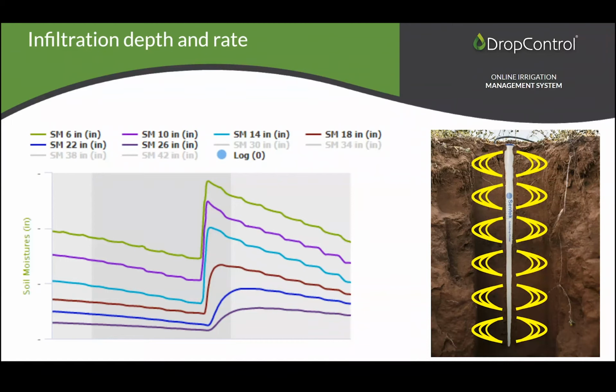The problem is that some of these probes, especially the ones with a smaller area of influence, will only read an inch or an inch and a half outside of the probe. So if you have an inch of slurry to each side, and a probe that only has a 1 inch area of influence, what you get is the reading of the water movement in the slurry. And that gets you to see basically preferential flow. I've personally seen that happen.